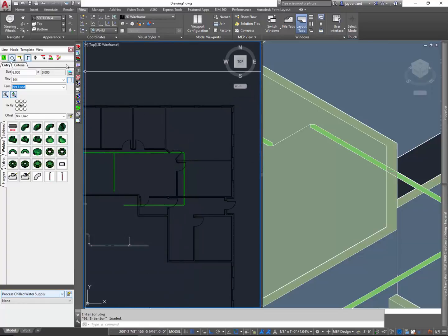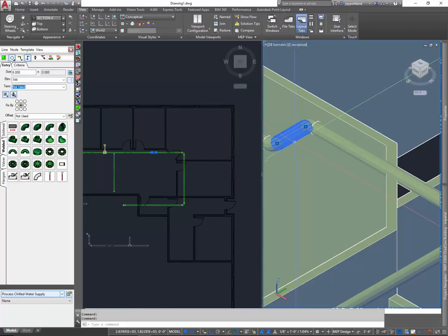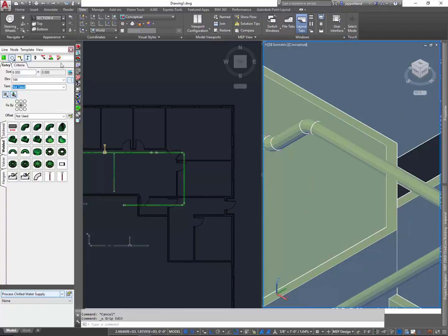Now, if I apply the three-dimensional items there, you can see how that automatically stretched back. So I love working with the design line itself. The problem when you work with this is you can disconnect the piping itself from the design line, so you're left with parts that are not connected properly. So I always erase the 3D and then reapply, work with just the center line and then reapply the 3D.